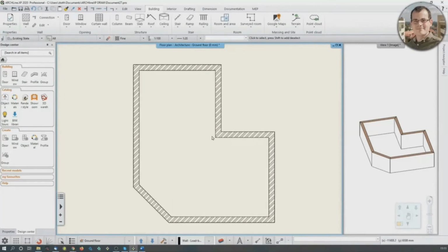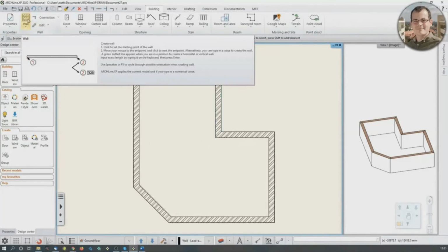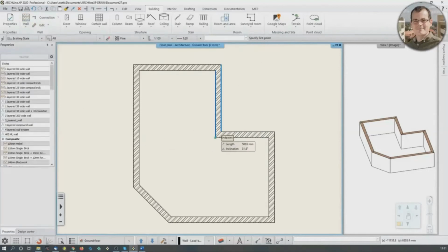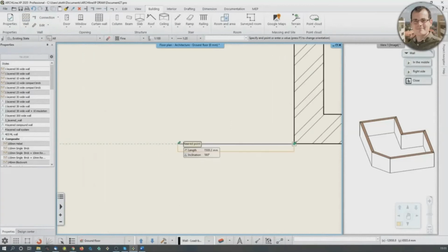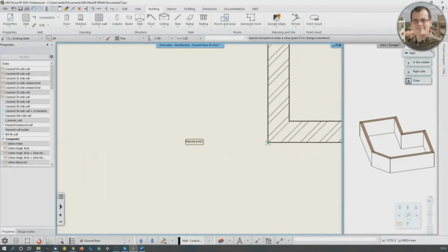So I want to have a partition wall over here. I'm just going to hit the wall icon and start a drawing point, but here's something weird and funny. If I draw the wall like this, it's not going to line up with my wall corner. So I have to switch the reference line. The line should stay where it is. That's the blue line I'm drawing, but the wall in relation to the line has to be flipped.